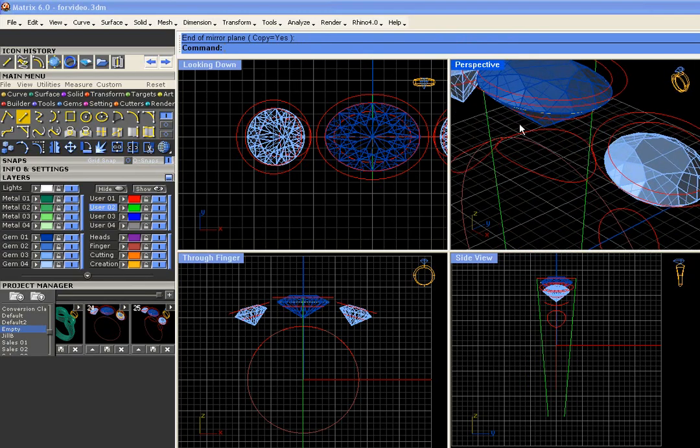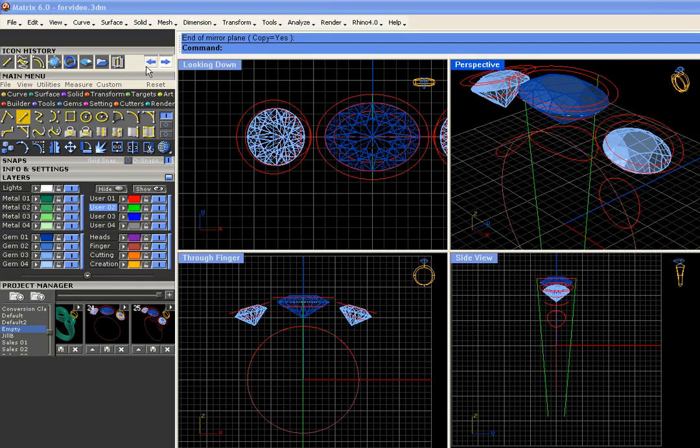Now, to see where the outside of the ring is going to be at the finger rail, we need the size of this curve right where it intersects the finger rail. Now, curve from two views is not going to do that because we're looking at an extra viewport. We're looking at the side view as well. So this curve has to be scaled down. We have to see the scale of it exactly where it hits the finger rail. The best way to scale a curve along two rails is, you guessed it, class, sweep 2.